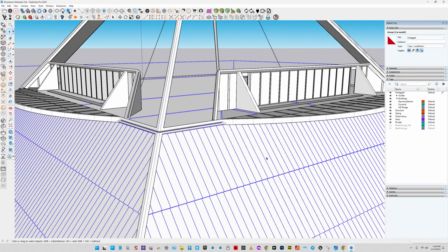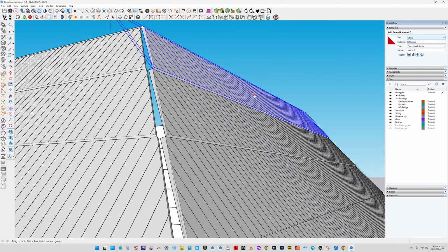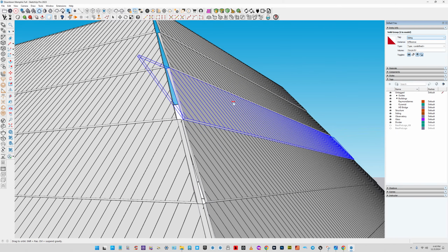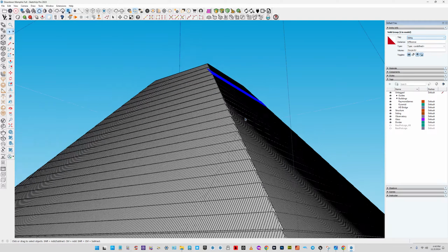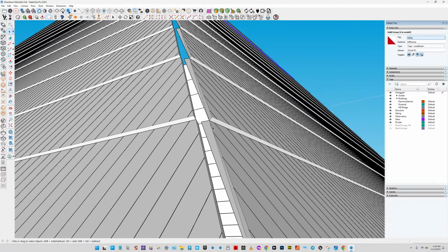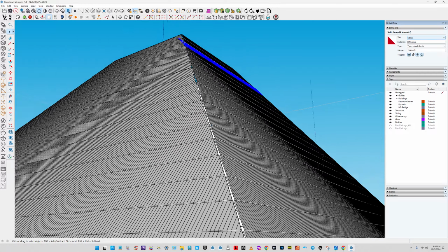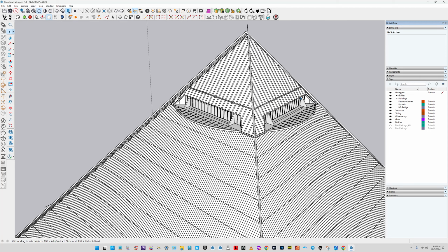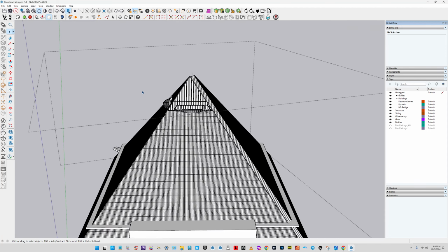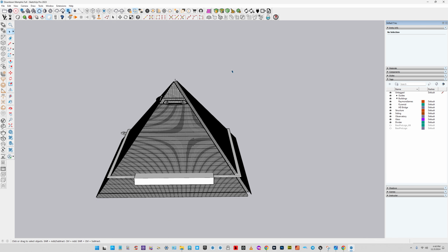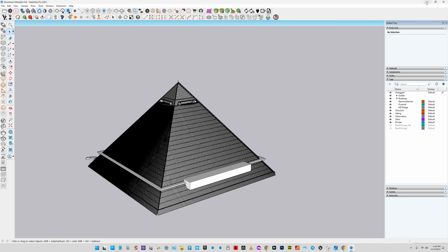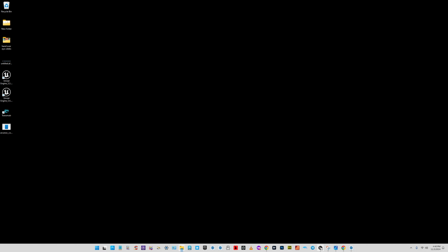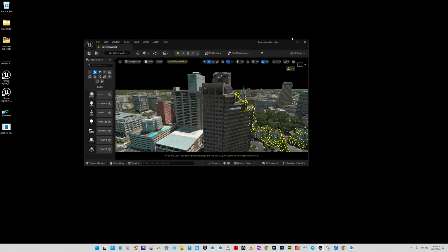Like all these individual assets have been individually modeled, right? So that I can get that higher fidelity detail instead of using PBR textures to fake the physical attributes of the pyramid. I went and modeled all those attributes. Okay. Once I did that, I did an export of the pyramid, right? And from another SketchUp file, open an empty SketchUp document, imported the assets that I wanted to import into the engine, and then I did a Datasmith export, and then I ended up with,